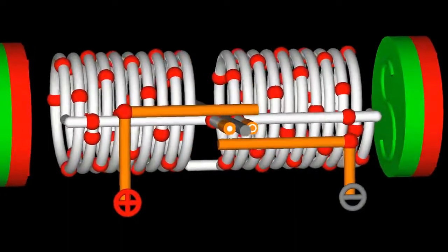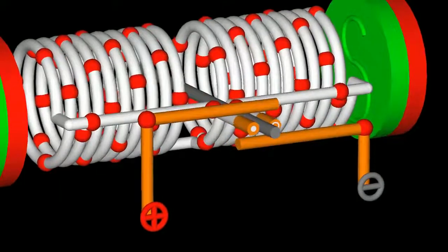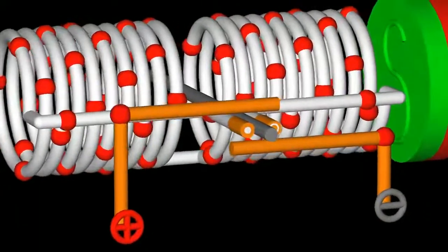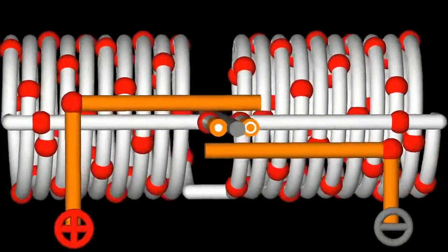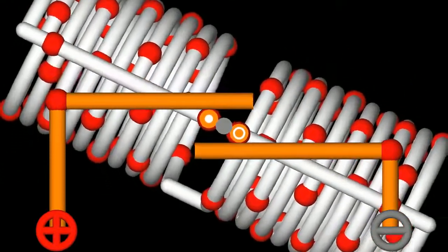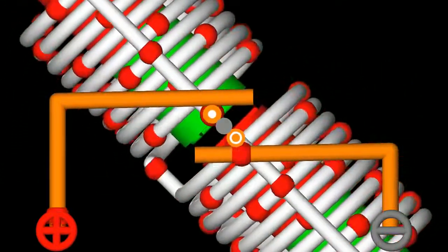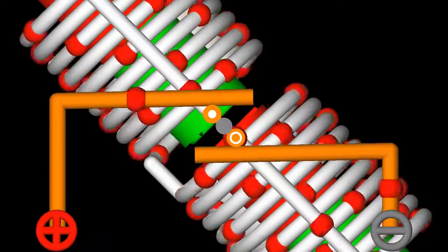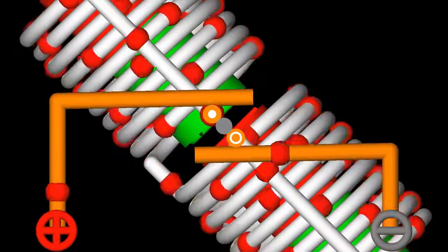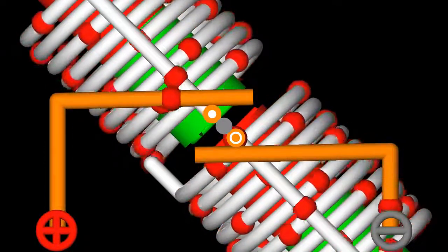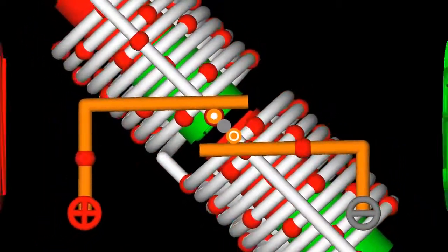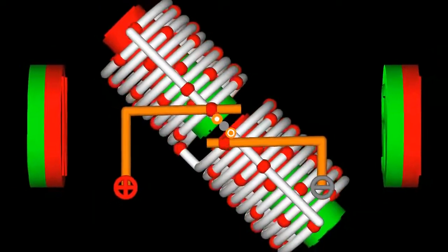With a rotary electrical switch, the polarity is swapped automatically, so we get the right timing for a continuous rotation. At this position of the electromagnet, none of the wire ends are connected to the power supply. When the coil is turned a few degrees, both ends make contact, each with a different terminal of the supply voltage. That results in a positive current flowing from that solenoid end marked with a dot to the second end marked with a circle, which is connected to the negative terminal of the supply voltage.